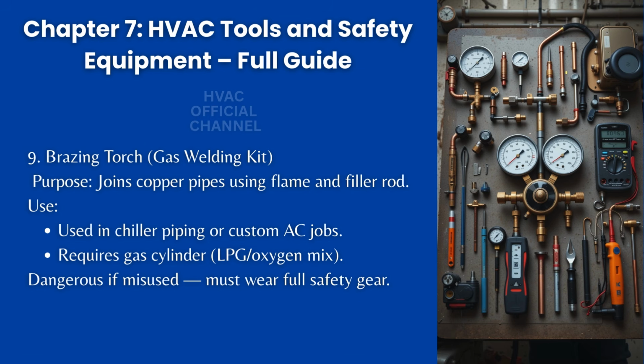9. Brazing torch. Gas welding kit. Purpose: joins copper pipes using flame and filler rod. Use: used in chiller piping or custom AC jobs. Requires gas cylinder, LPG, oxygen mix. Dangerous if misused. Must wear full safety gear.